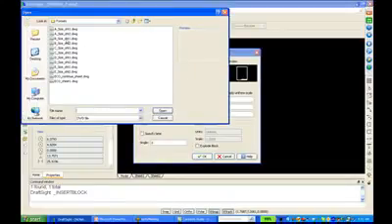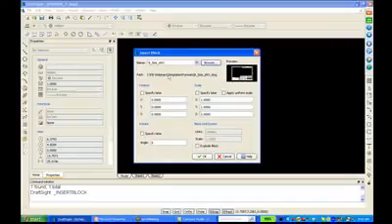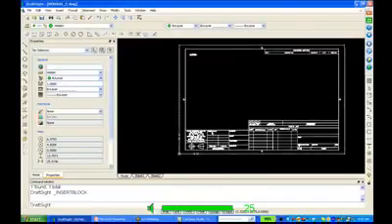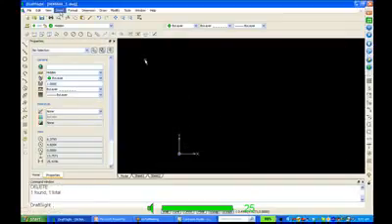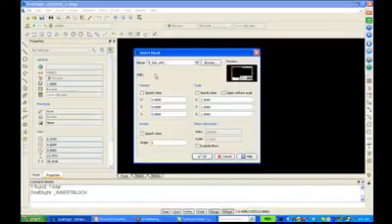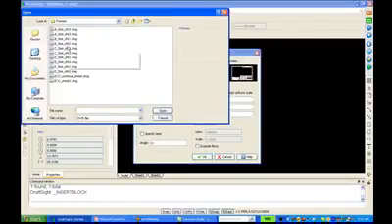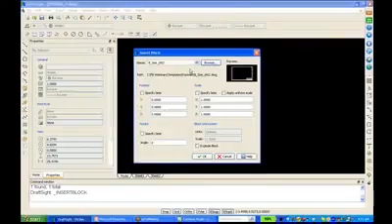Any drawing that you create, you can insert into your file as a block. You can see that this is just one entity. It's a block. If these drawing borders had blocks associated with them, they would come into the drawing as well, so they would be stored in this list of blocks that are available.